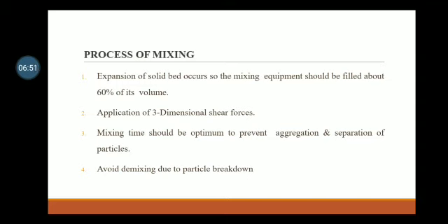Then process of mixing: expansion of solid bed occurs, so the mixing equipment should be filled about 60% of its volume. Application of three-dimensional shear forces. Mixing time should be optimum to prevent aggregation and separation of particles. Avoid demixing due to particle breakdown.